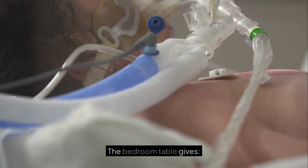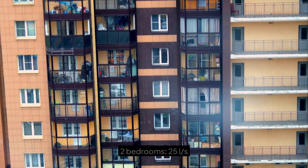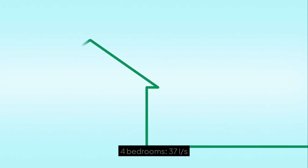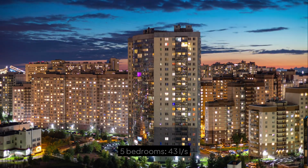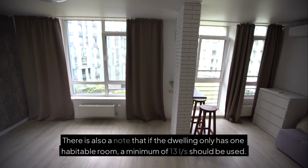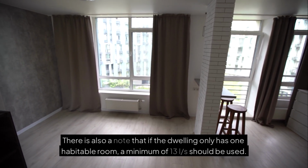The bedroom table gives 1 bedroom 19 liters per second, 2 bedrooms 25 liters per second, 3 bedrooms 31 liters per second, 4 bedrooms 37 liters per second, 5 bedrooms 43 liters per second, and then add 6 liters per second for each additional bedroom beyond 5. There is also a note that if the dwelling only has one habitable room, a minimum of 13 liters per second should be used.